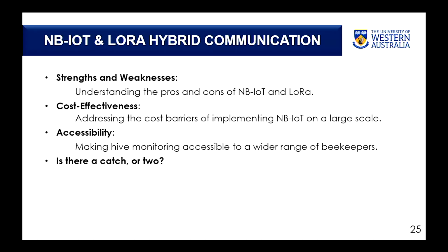You have so many devices which are connecting to the one gateway, and only that router has a DSL connection. So NB-IoT acts as a backbone of the transmission, and for the local network we use LoRa. But to come to this point, we had to understand the benefits of both LoRa and NB-IoT. With this, we achieve cost effectiveness, and we also make beehive monitoring accessible to a wider range of beekeepers.